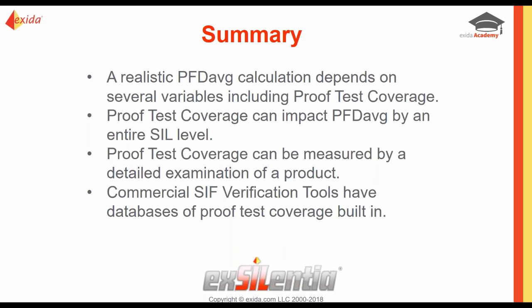You can know your proof test coverage by FMEDAs, by buying certified products or doing the FMEDAs yourself and evaluating the diagnostics and the coverage in the FMEDA itself. You can do that using tools, which makes your life a lot easier, or you can buy certified products. And we know you might not be able to do your proof tests at operating conditions. You might not be able to include a leak test, but do what you can and just use realistic numbers.